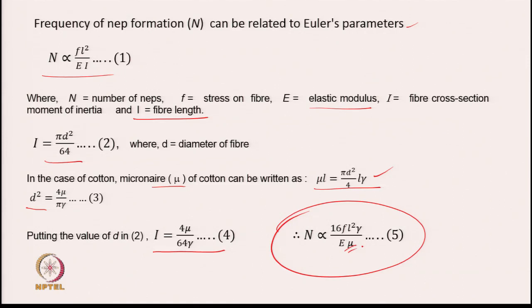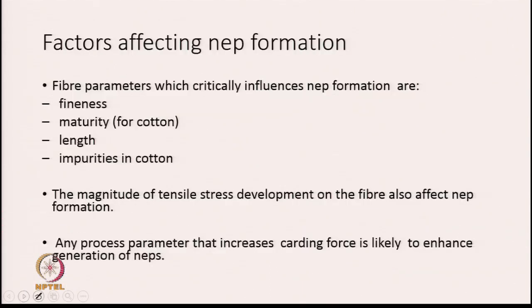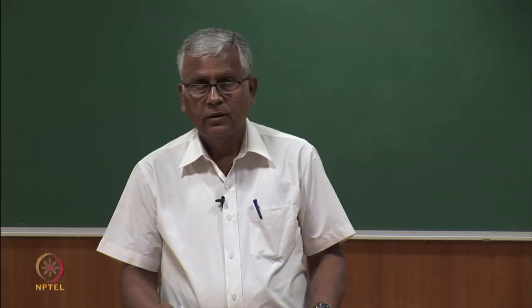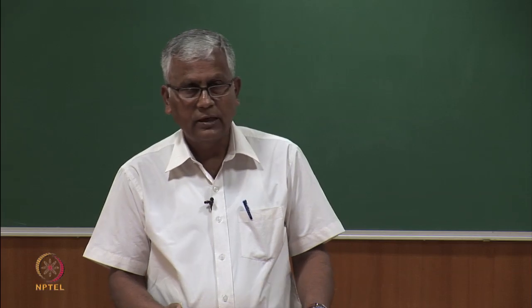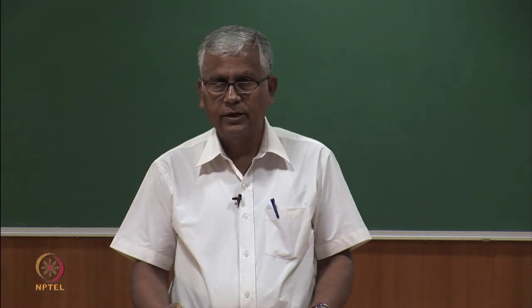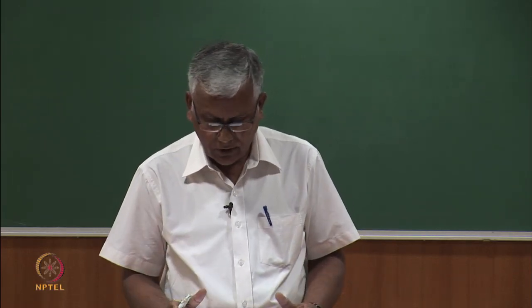So, what we see here is that the number of NEPs that get formed is a function of stress level and it increases with length of the fibers. So, we have to be very careful, for a given fiber, what is the length of it and what is the level of stress that is acting on the fibers during processing of the fibers on the machine.